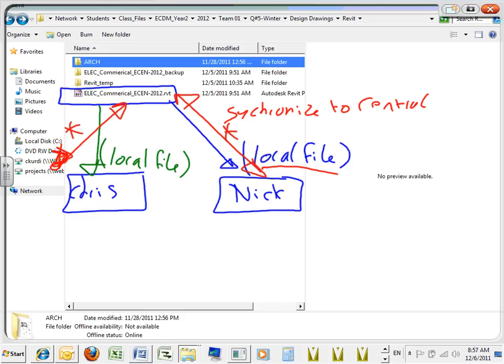This is very important, guys, in terms of how the system is laid together. The only person that can access this folder is me, because I can make you all guys one central file, but we minimize the damage. So I have it shared here. The same thing, I can go between any of your folders, guys. So I usually go there to look at your stuff. And when I'm done, I say relinquish all. When you synchronize, relinquish means everything that you touch that you own right now, you give it back to the central file so somebody else can touch it and work on it.